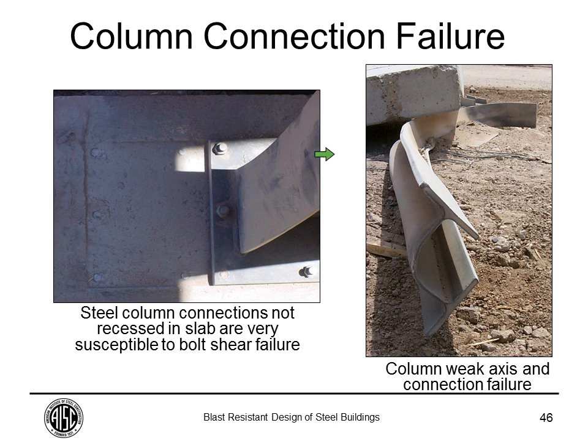You can see on the right, the column is bent in all different ways, but it has significant curvature, so it clearly went into the plastic range, and the bolts right here weren't able to take the load. So generally, it's a good practice to do a recess and grout fill compact so that the lateral reactions are basically taken by shear and straight into the floor diaphragm.